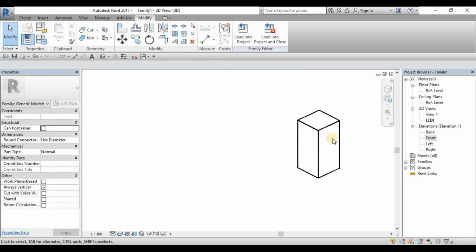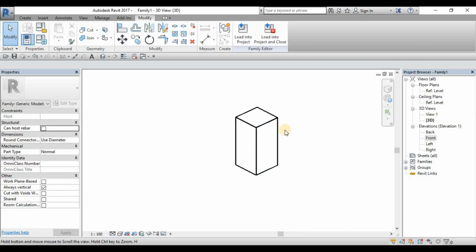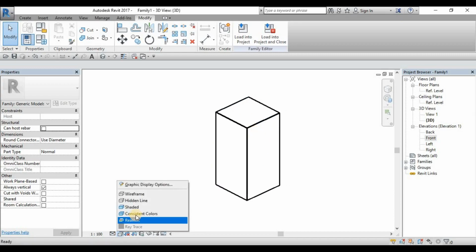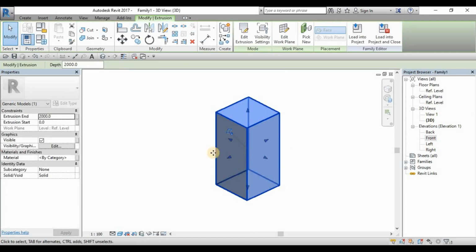Okay, so that is our Revit Family basics and box. One last thing, we need to assign a material for our box. When I go to shaded mode, these are all gray, so what I want to do is apply some material to it. I click the element or the form, and as you can see in our instance parameters, we have this material property. So what I can do is just assign a material first.